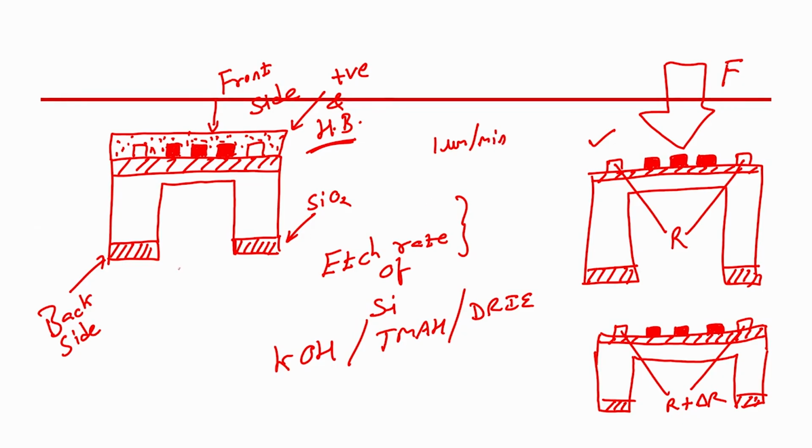Then how many minutes you require to etch the silicon to have finally whatever the thickness of diaphragm you want for your strain gauge. Suppose your silicon thickness is 500 microns, assuming that you are using a 4-inch diameter silicon wafer, and then you are etching silicon which is about 400 microns. So, remaining is your 100 microns, the thickness of the diaphragm is 100 micrometer.